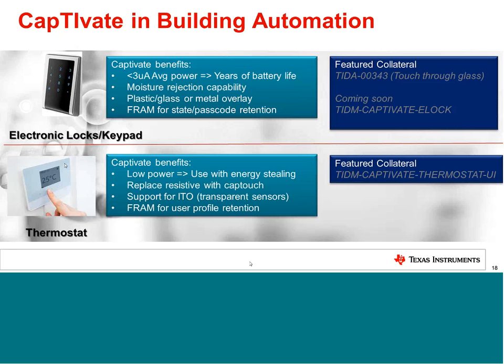It's a PCB, but it's transparent. You can actually look through it. And you can implement CapTouch buttons on the ITO. And when you throw that on the display, it looks like a touchscreen controller, but it's a lower cost solution because you're just using buttons on top of an ITO, on top of a display panel rather than a full touchscreen controller.